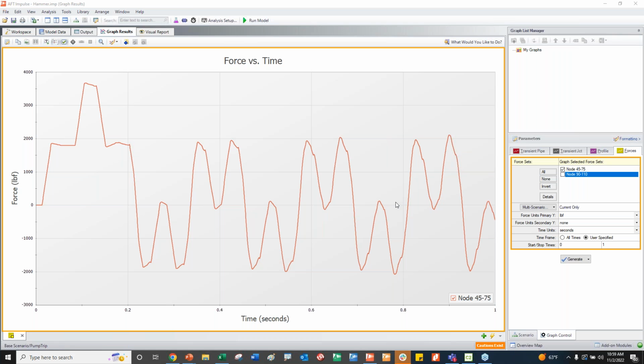One question: how do you find solutions for waterhammer failures? It completely depends on the engineer, or any standard method like a surge tank. Yes, it depends on the criteria of the engineer. A surge tank is usually a good solution. It's easy, but sometimes it's not applicable or too expensive.